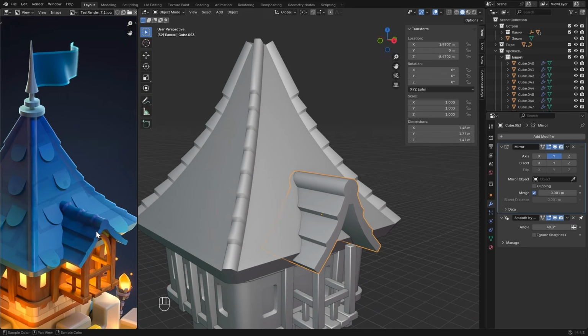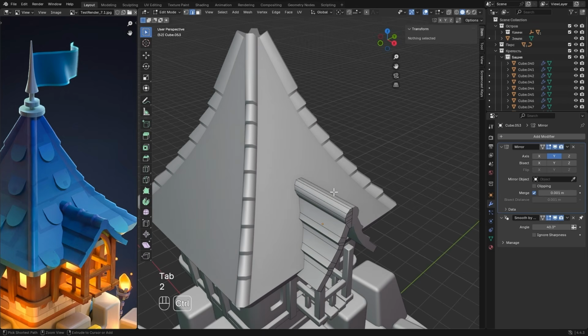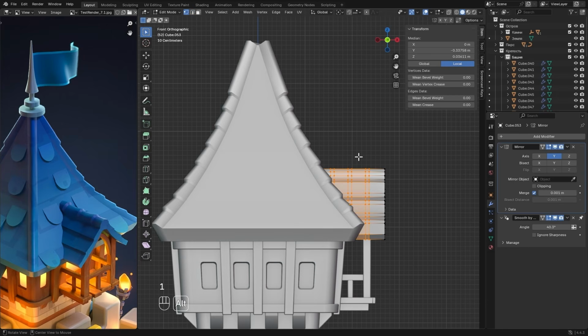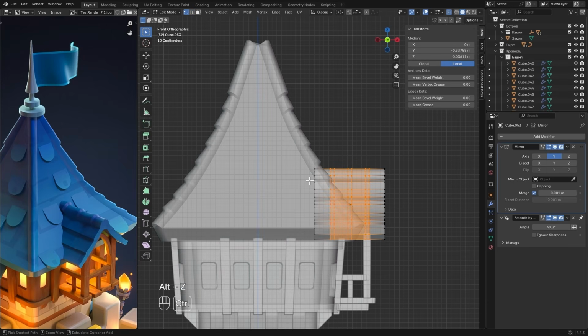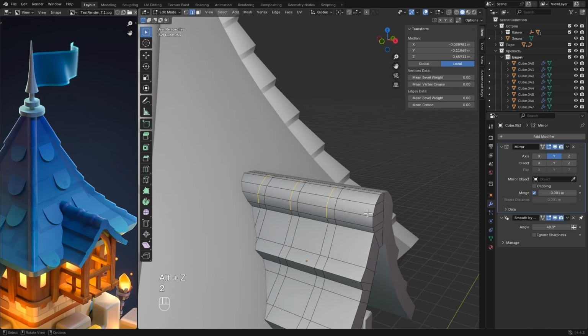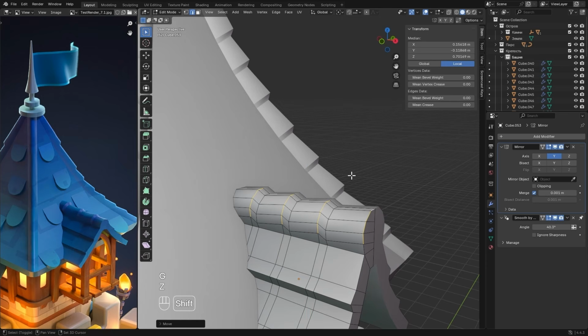We can add more detail to the ridge cap. Go into Edit mode, and let's add a few loop cuts. Press Ctrl+R, set it to 3, and split them with one segment. Press Ctrl+B, split them. Switch to the Side View, Vertex Select, X-ray mode, and hold Ctrl to deselect this bottom area. Let's also deselect these vertices and these ones over here. In Edge Select mode, add these edges to the selection, and let's move these selected areas along the Z-axis, press G, Z, and lift them.